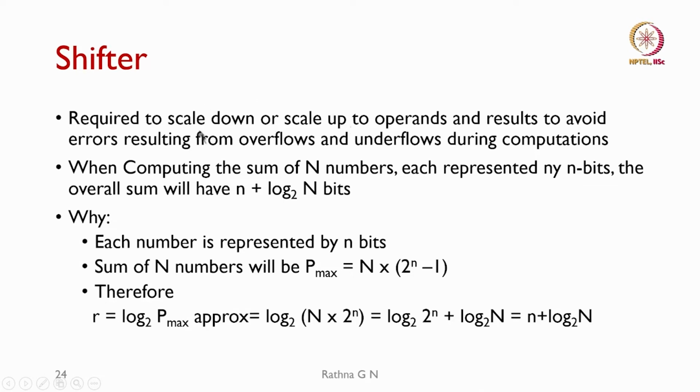So, we need that scale down there, and then once the result is there, we may have to scale it up back to the previous scale-down value and then give the output. So, this avoids our overflows and underflows. Overflow, all of you must know, is when the value is much more than what can be represented. Underflow is when it goes below the maximum negative value that has been provided.